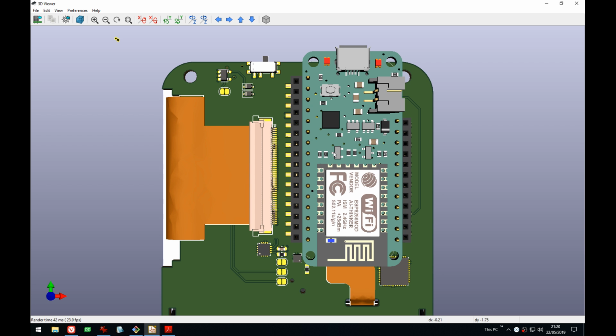No, so yeah, it makes sense to not go like, if you know you're going to use 100 milliamps, it makes sense to use 250 or 500 milliamps and not 3 amps, just because of the size. A 3 amp LDO is usually larger because it has more energy to dissipate. So you just have to know what you need, and for those you have to read data sheets and specs and so on. So once you have those 3 things: voltage in, voltage out, and then current,